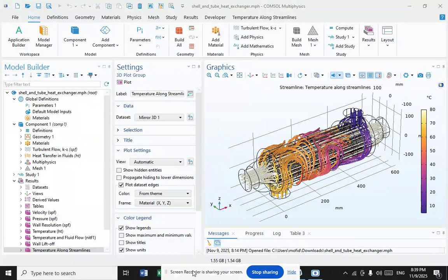Plate and shell. A third type of heat exchanger is a plate and shell heat exchanger, which combines plate heat exchanger with shell and tube heat exchanger technologies. The heart of the heat exchanger contains a fully welded circular plate pack made by pressing and cutting round plates and welding them together. Nozzles carry flow in and out of the plate pack. This is the plate side flow pass. The fully welded plate pack is assembled into an outer shell that creates a second flow pass.